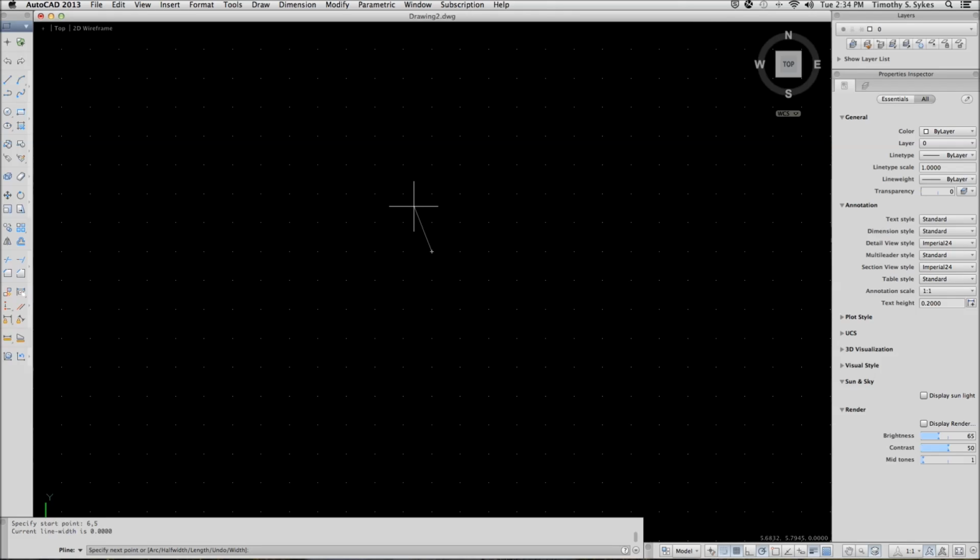And then I want to change the width. One of the wonderful things about polylines is that you can draw a line with width. Notice you have quite a few options here. We'll face quite a few more options as we go. To get familiar with these options, refer to section 12.1 in your textbook.